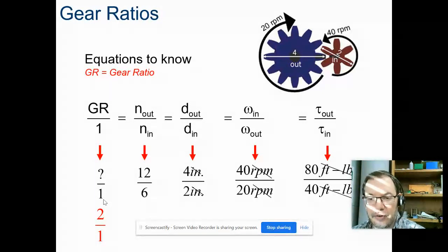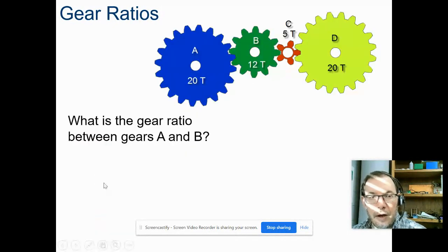And so what happens is they have a gearbox, and that gearbox is going to have a gear ratio that's greater than 1, and it actually is quite a bit greater than 1. I don't know what the exact number is, but it's a very big ratio. What it's doing is taking that small motor that has high RPM and low torque, and taking that RPM way, way down, and then increasing the torque quite a bit. So you get the torque up enough to where it can drive those little kids around, but the speed is much slower, and so they're not going to drive as fast, but they can definitely have enough torque to move them.